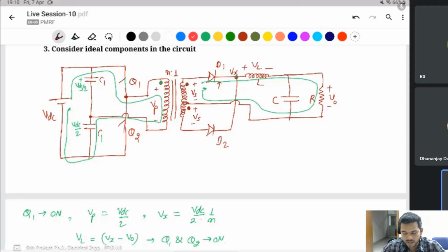If you read about the inverter, the same thing applies there. Here also we require the capacitors. Yes, same everywhere, in the push-pull and forward converter. Because Q1 and Q2 are not exactly the same, for manufacturing there are some differences or manufacturing errors, and the flux walking phenomenon occurs. Will C1 and C2 be equal? Yes, this one is the same. If it is not the same, then VDC will not be equally divided by 2.